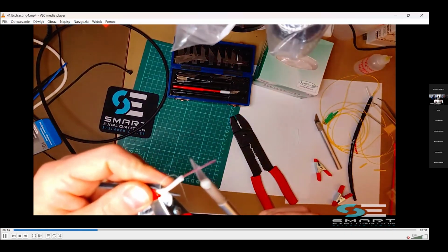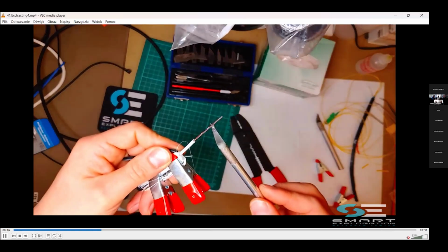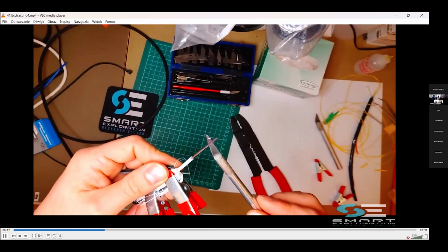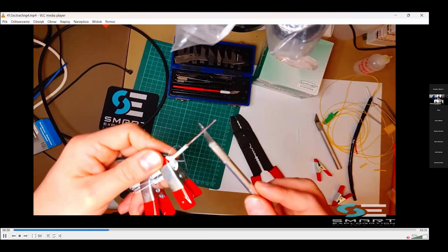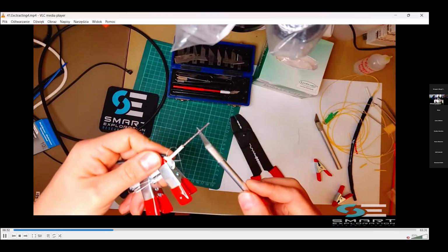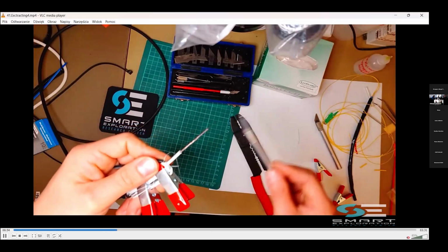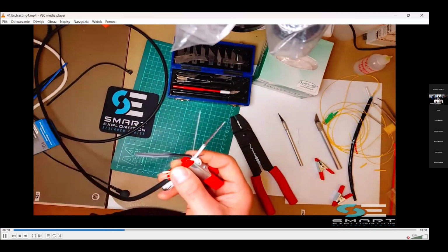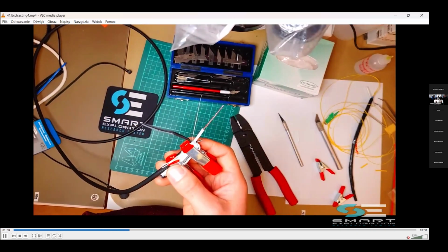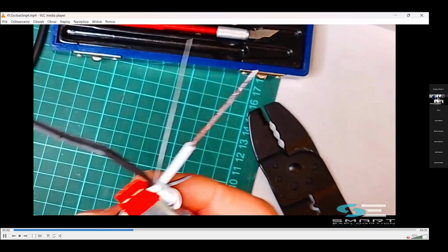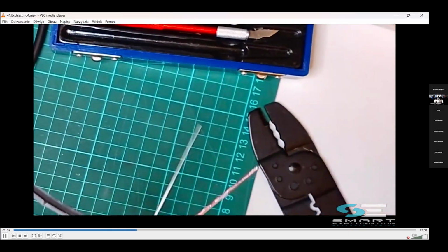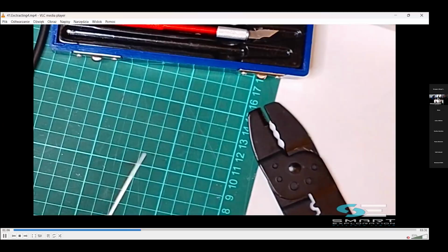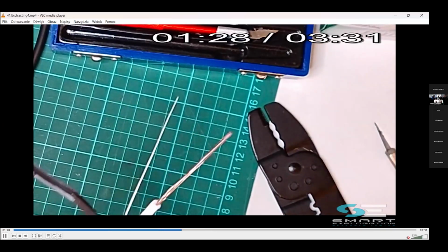The cables have 4 cores, 8 cores, 12 cores, depending on the cable manufacturer. And these cores, these fibers are layered with an additional substance that is blocking the water from going inside. And we have to clean everything and remove this substance.